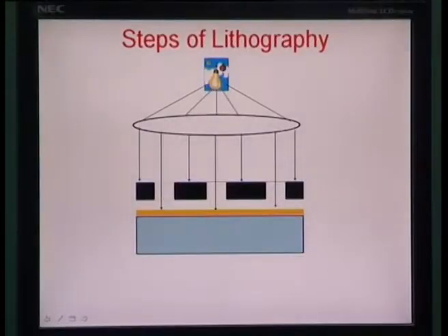Then with a lensing and focusing arrangement, you draw parallel beams of light to fall through this mask onto the wafer. The light passing through the transparent regions hits the surface, whereas light blocked by the opaque portion of the transparency does not travel, and so the areas exposed are just below the transparent features, and thus the feature on the mask is translated onto the resist layer.